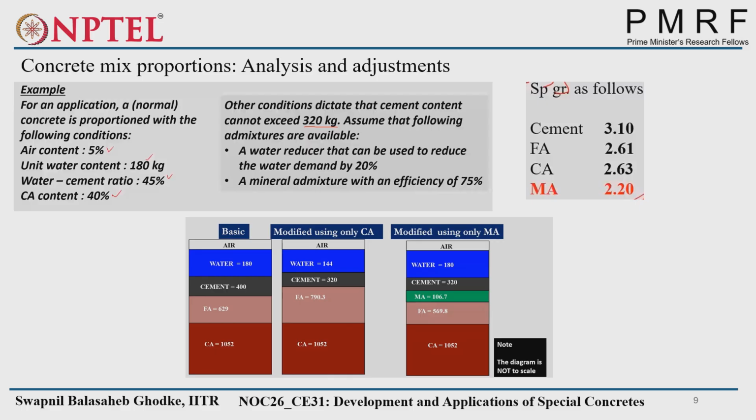What are the equations? What happens? We have cement. We add water. Directly, we will get the CSH. C2S will react with H2O, C3S will react with H2O, and we'll get the CSH and CH, calcium hydroxide, as a byproduct. Whatever byproduct CH we are getting will react with the silica content available from the mineral admixture, and that silica plus this CH will convert into additional CSH.